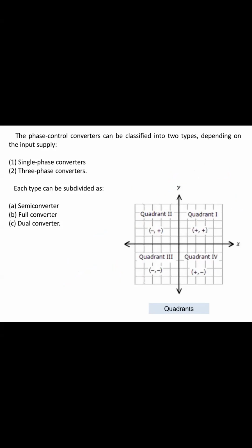You can see here this is the first quadrant converter. In the first quadrant converter, we have an SCR as well as a normal diode. First quadrant converters are one quadrant converters. They contain controlled as well as uncontrolled rectifiers in different circuit positions. Uncontrolled is the diode, controlled is the thyristor. So this is the first quadrant, or one quadrant, converter.